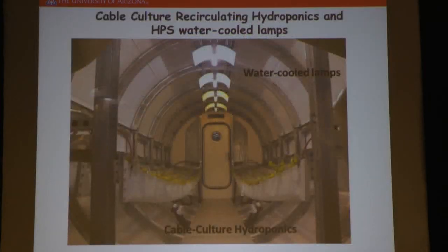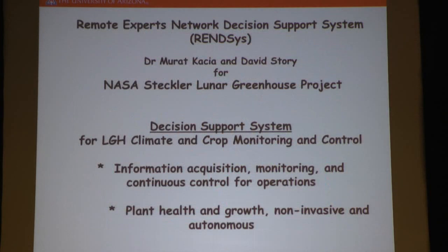The two focus items are the water-cooled lamps and the cable culture hydroponic. That lamp made it possible. High pressure sodium obviously will not be around forever. LEDs are coming along. They needed to be developed for the past 10 years, so they got the high pressure sodium. Let's put water cooling on LEDs and move ahead. Then the cable culture hydroponic, a lightweight nutrient film technique, more or less. Alan Cooper would cringe if he heard me say that, because it's a vertical system, not a horizontal NFT. But it works very well, lightweight, grows the plants.